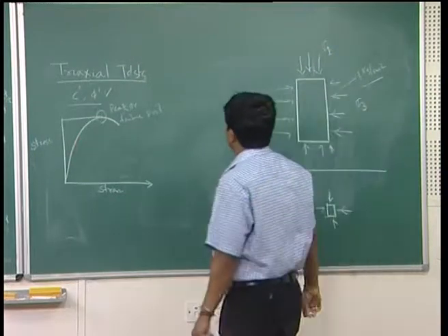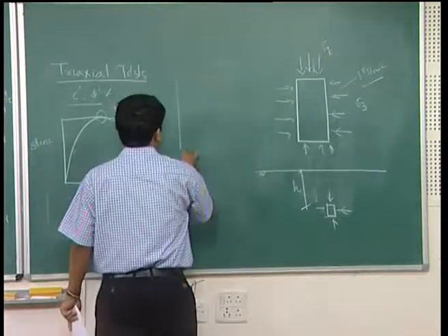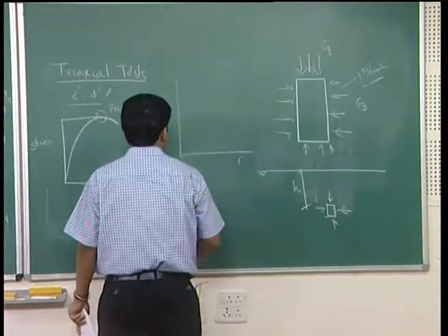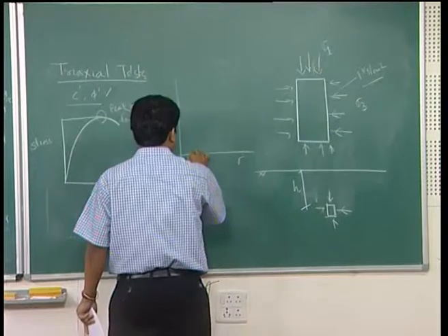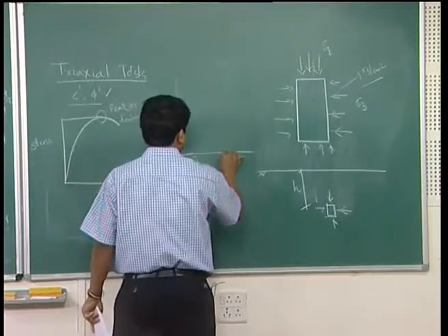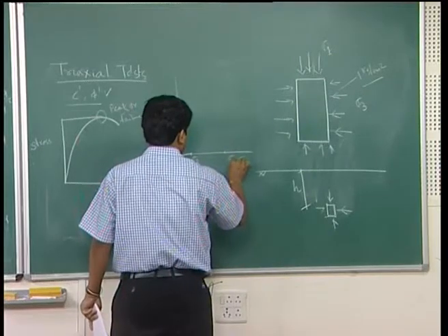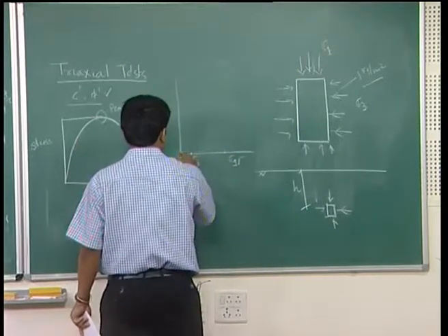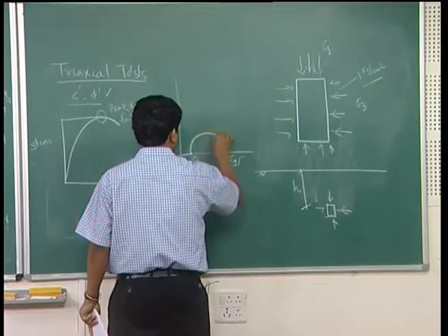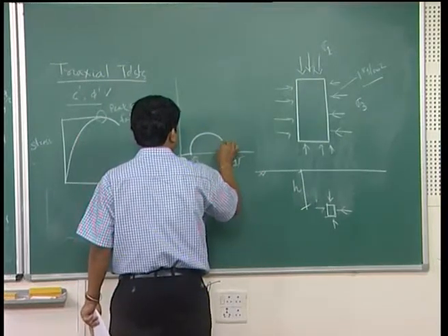The moment you want to draw the Mohr circle, what will you do? You will take shear stress versus normal stress, take your sigma 3 and your sigma 1 from the coordinate axis origin. With this, draw the Mohr circle, half of the Mohr circle.